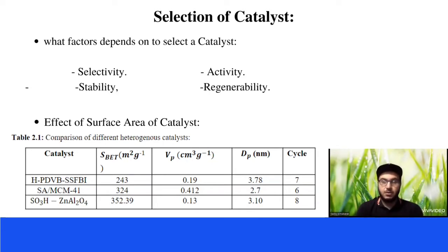Also, another idea we need to consider as an important factor while selecting the catalyst for a specific reaction, based on scientific theories, is that the porous structure enables the solid to have a higher surface area. Moreover, the size and number of pores determine the internal surface area, and pore size also determines the accessibility of reactant to the active sites and the ability of diffusion of product back to the bulk fluid.